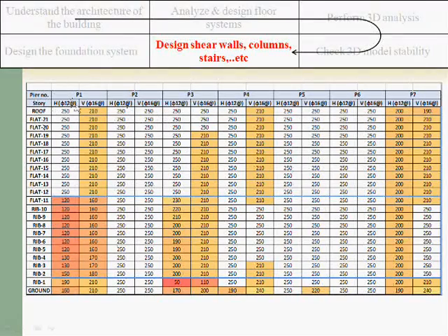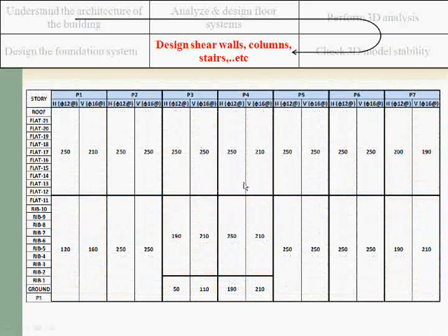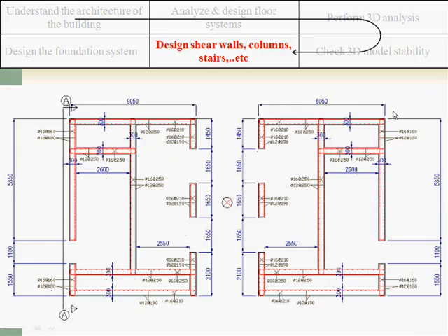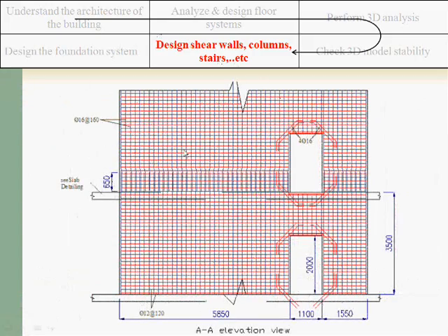This is the result for each pier, as you can see, for each floor. And this number, for example 120, comes from the 6 or 8 load combination that we have used in this floor. As you can see, this floor, which is the 11th, has more reinforcement than the first or second one. This is because it depends on the torsion and shear, and not only the axial load and the moment. After that, we group these values and take them for the detailing, as you can see in this drawing. This is the elevation of the detailing to show the opening with the slab.